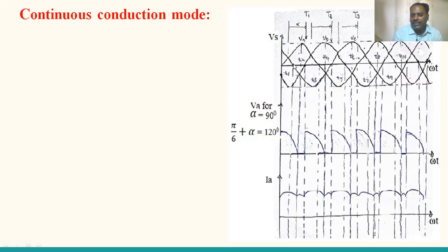In this three-phase supply, every pulse exists for a 60 degrees duration: 0, 60, 120, 180, 240, 300, 360, it keeps on increasing. So you have to recognize the phases VA, VB, VC. That means every 180 degrees there are 3 pulses. Therefore the ripple frequency is very high and the filtering requirements are very small. Also, most of the time this drive operates in continuous conduction.